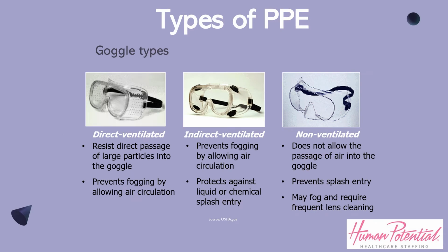Safety goggles are used as primary protection to shield the eyes from heat hazards. Goggles form a protective seal around the eyes, preventing objects or liquids from entering under or around the goggles. This is especially important when working with or around molten metals that may splash. When employees are exposed to high temperatures, additional protection beyond that offered by primary protectors may be required. Use safety goggles in combination with a heat-reflective face shield for severe temperature exposures.